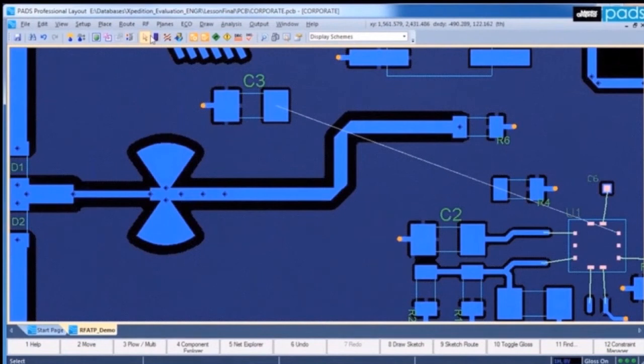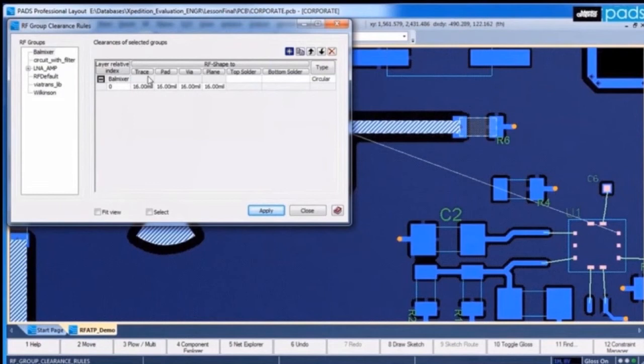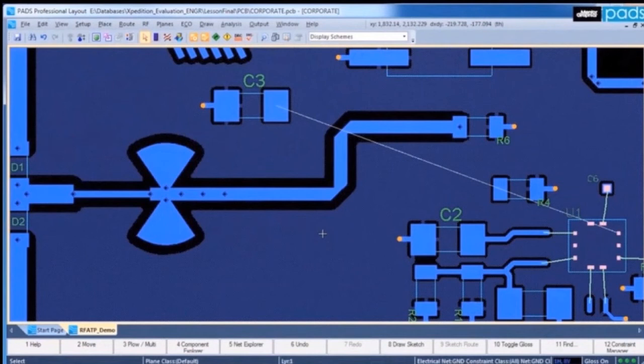I will now set a Z-axis clearance for the layer below the meander. This is to keep traces, planes, and vias away by 40 mils. When routing away from this component, you will notice that the trace is obviously not allowed to cross the meander on the same layer.